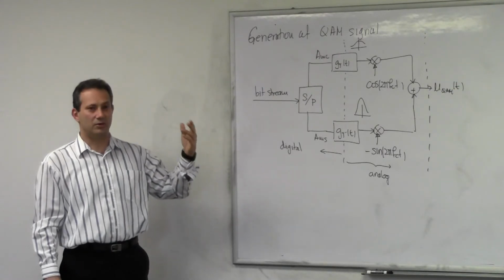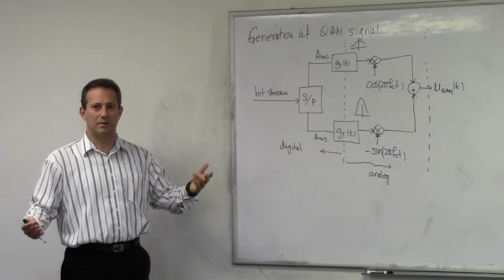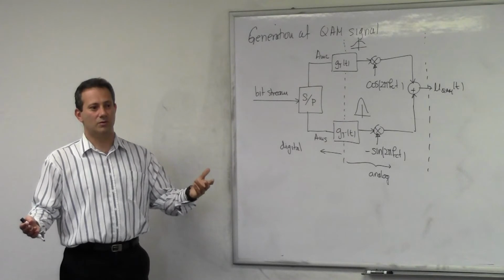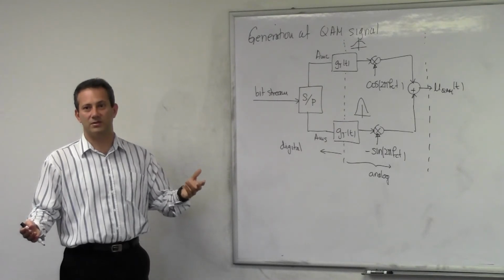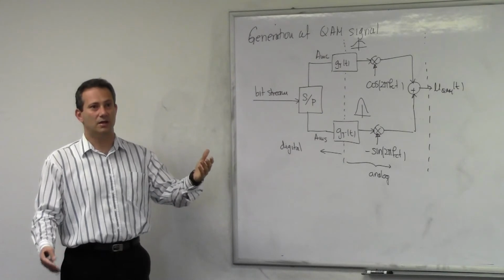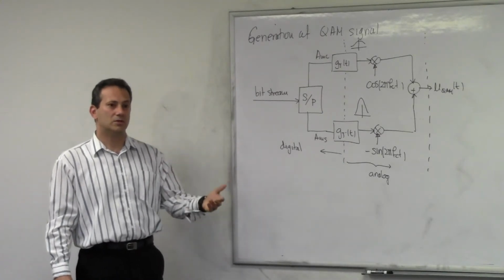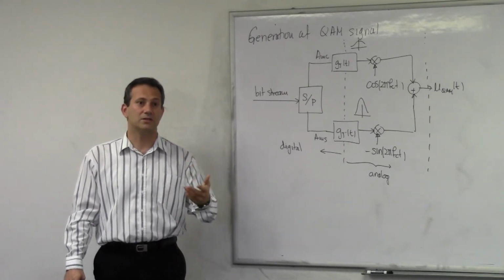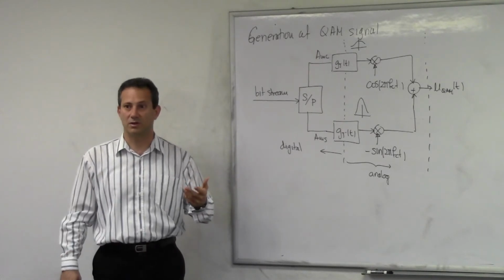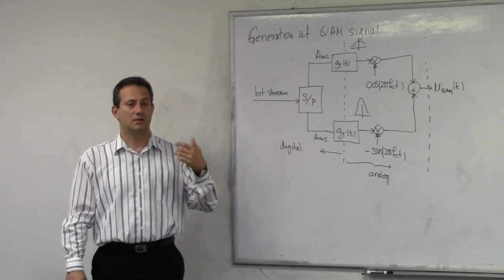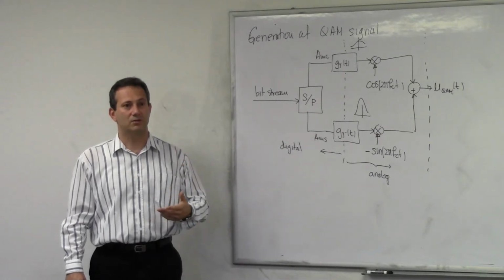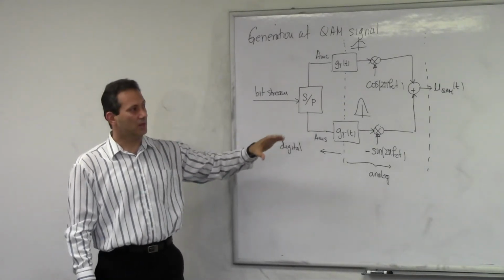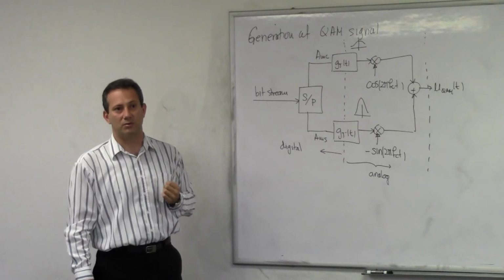Although theoretically this is pretty cool and you can come up with a lot of interesting theoretical results, in practice we have two naturally given basis vectors. One is cosine and the other one is sine. And we can modulate them in two similar but a little bit different ways. One is we modulate them using just a phase, which means all our constellation points are on a circle. They have the same energy. And the second one is we modulate them both in phase and magnitude, in which case our constellation points are distributed throughout the signal space, and we end up with quadrature amplitude modulation.